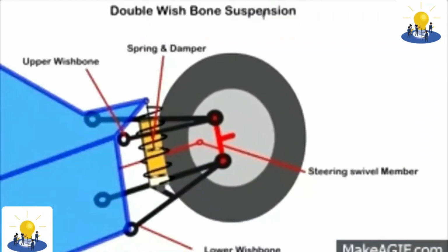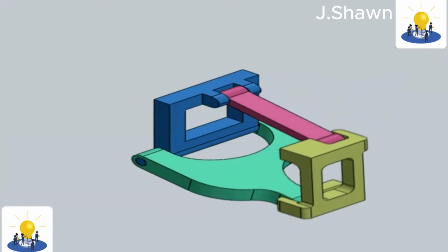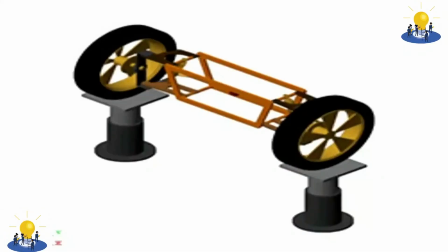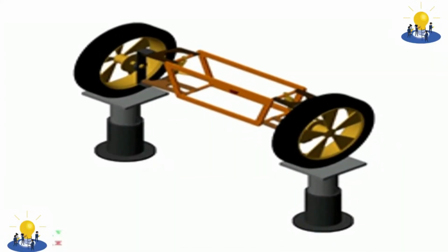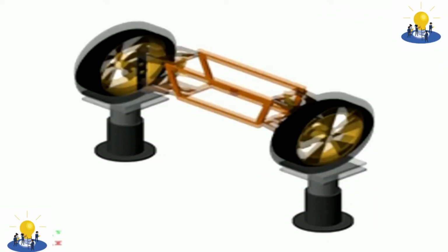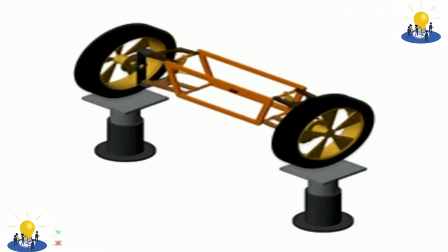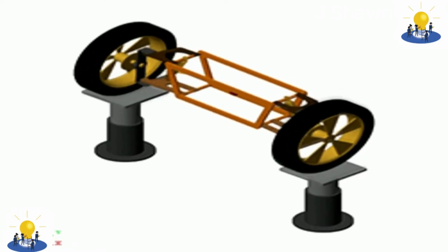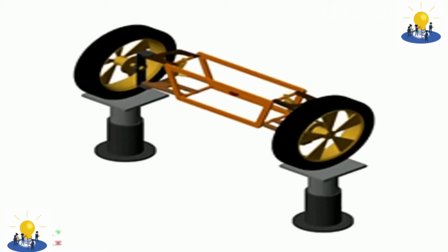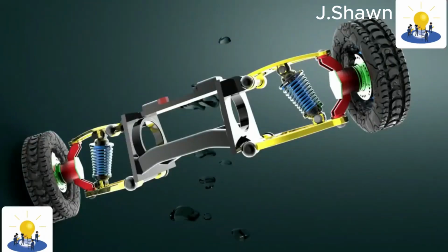At the knuckle end, single ball joints are typically used, in which case the steering loads have to be taken via a steering arm, and the wishbones look A or L-shaped. An L-shaped arm is generally preferred on passenger vehicles because it allows a better compromise of handling and comfort to be tuned in. The bushing in line with the wheel can be kept relatively stiff to effectively handle cornering loads, while the offline joint can be softer to allow the wheel to recess under fore-aft impact loads.